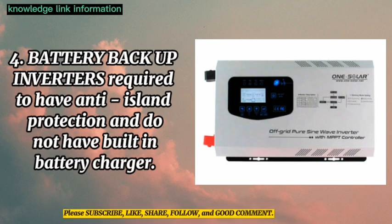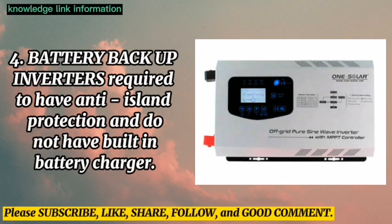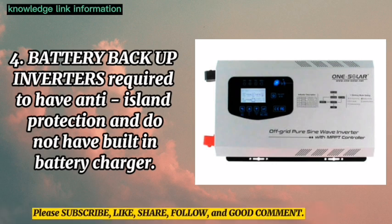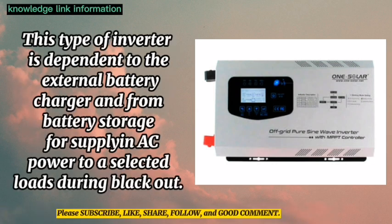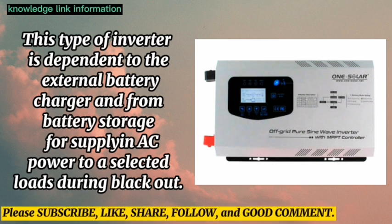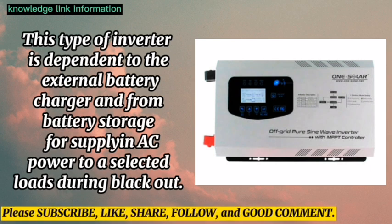Number 4. Battery backup inverters are required to have anti-island protection and do not have a built-in battery charger. This type of inverter depends on an external battery charger and on battery storage for supplying AC power to selected loads during blackouts.